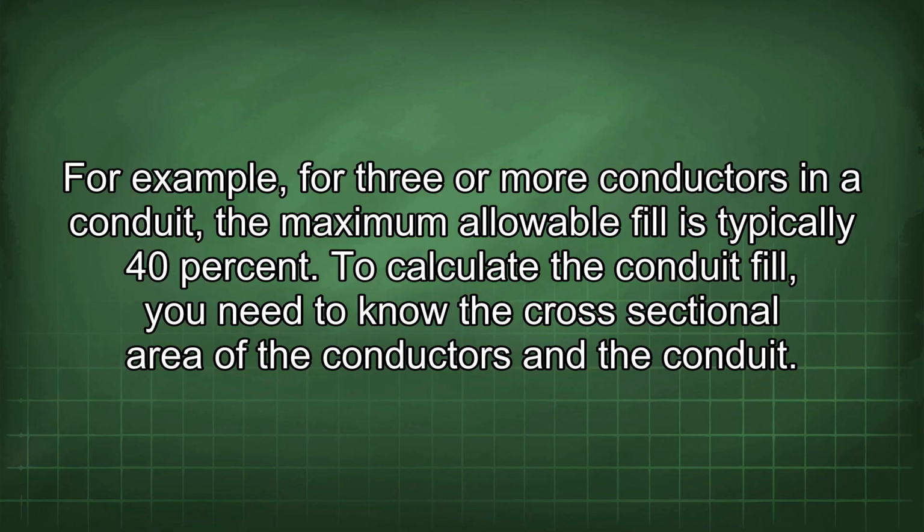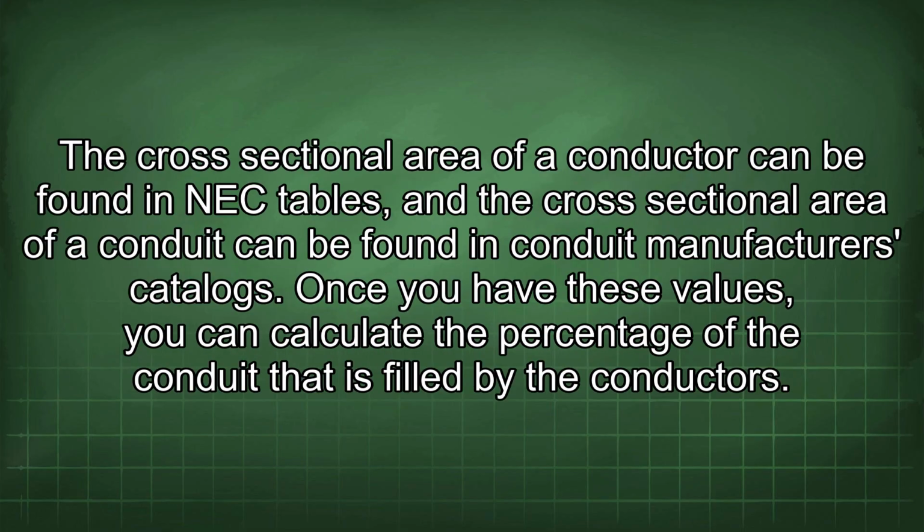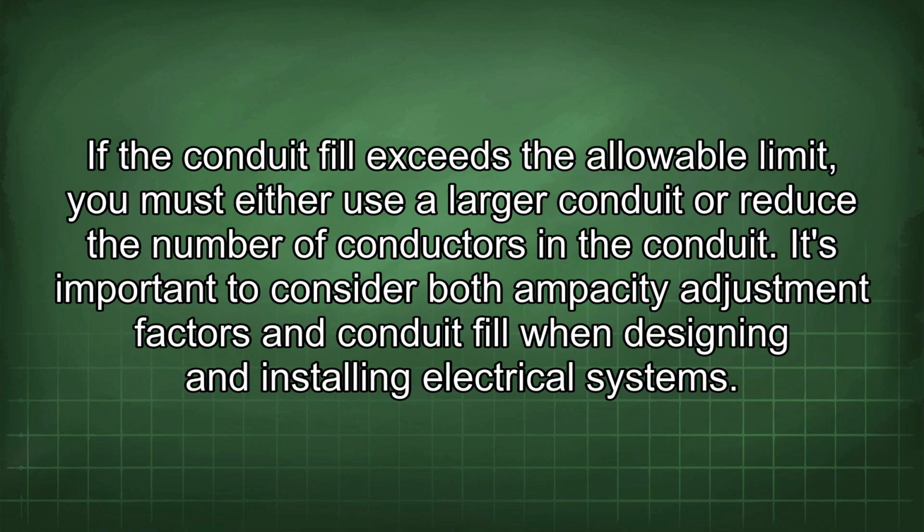To calculate the conduit fill, you need to know the cross-sectional area of the conductors and the conduit. The cross-sectional area of a conductor can be found in NEC tables, and the cross-sectional area of a conduit can be found in conduit manufacturers' catalogs. Once you have these values, you can calculate the percentage of the conduit that is filled by the conductors. If the conduit fill exceeds the allowable limit, you must either use a larger conduit or reduce the number of